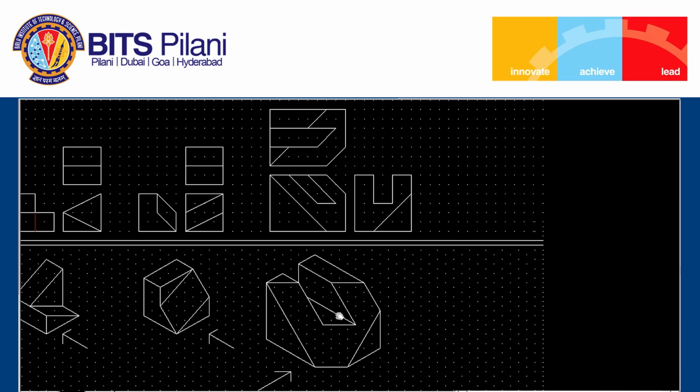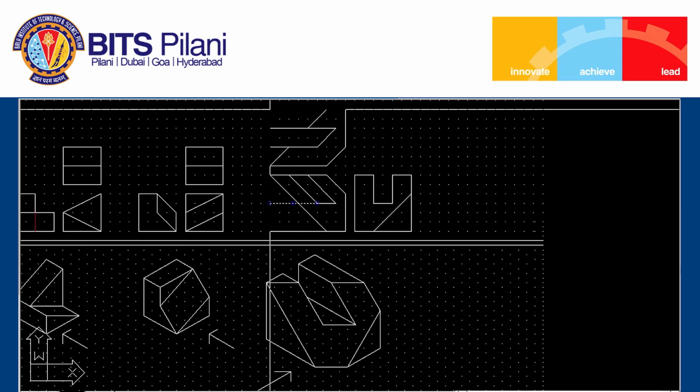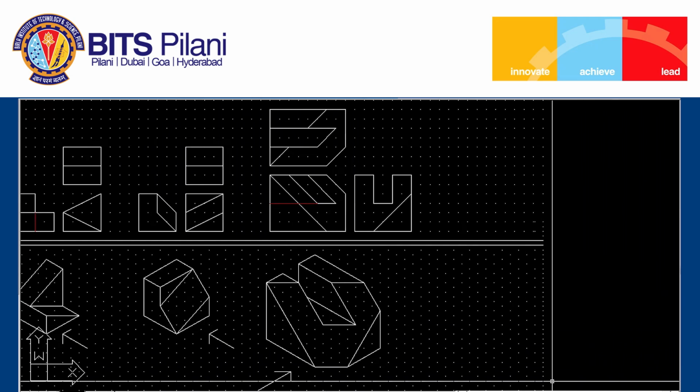This part will be visible, but the later part will not be visible. So that we have to show here, and that will be shown with the hidden line. Hidden line we will indicate with the red color. So, this line is nothing but this horizontal principal surface. Now, all surfaces are satisfied here.